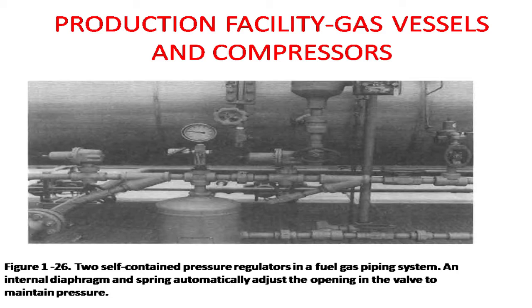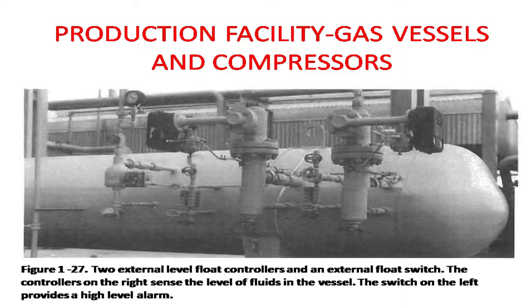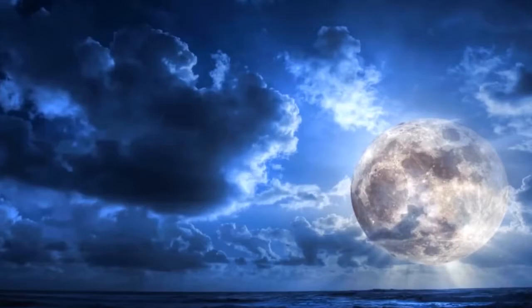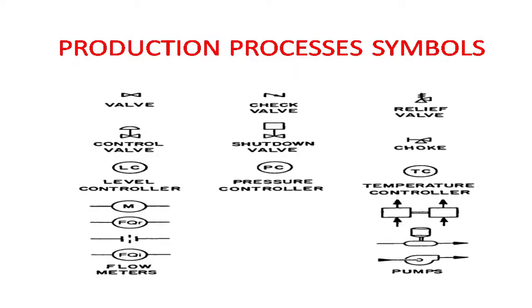In some instances, there will not be enough gas separated. Under some conditions where there has been only a small pressure drop from the upstream vessel, where the crude GOR, gas oil ratio, is low, it may be necessary to add gas to the vessel to maintain the pressure control at all times. So that's very important.